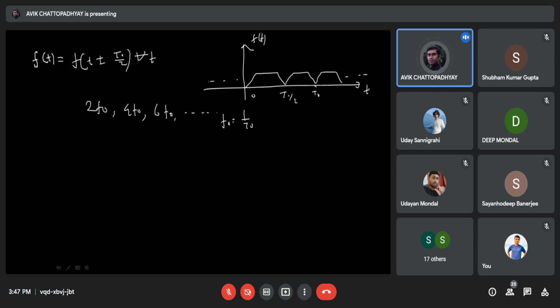But if we look at it like this, then of course these terms are going to be present, which can be read in relation to the original fundamental frequency as: only the DC and the even order terms are there. All odd order terms, or harmonics, are absent.